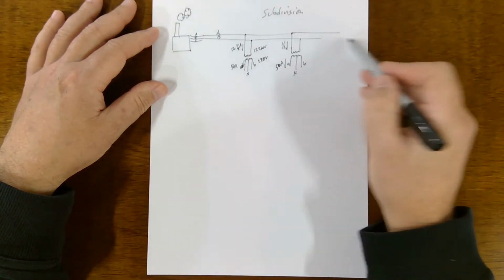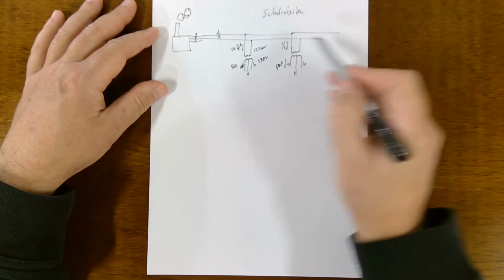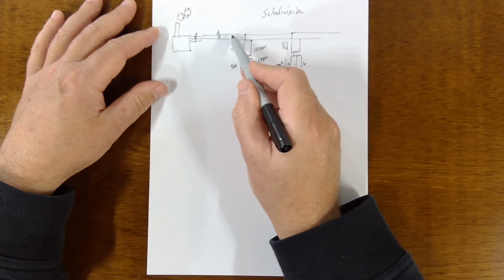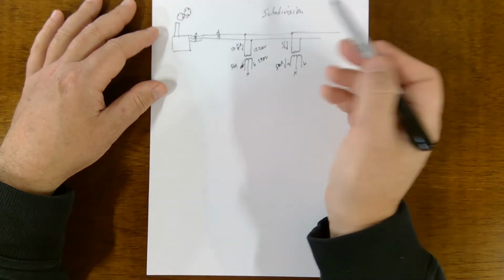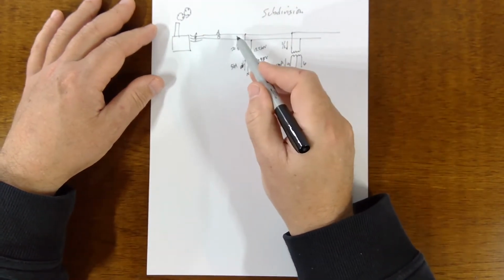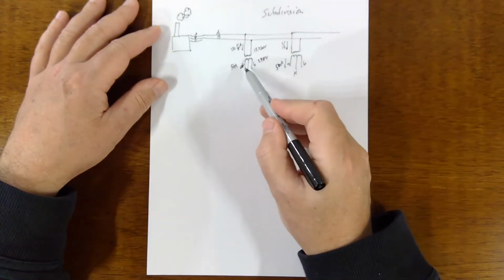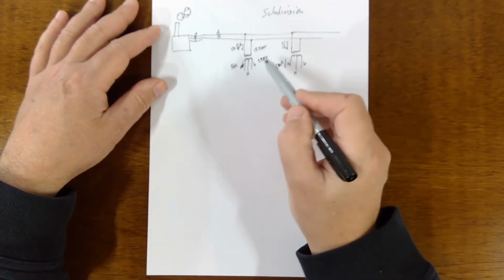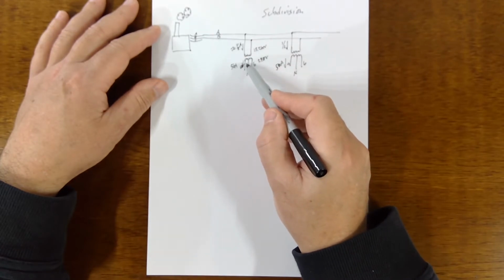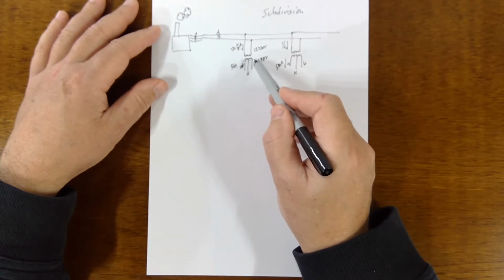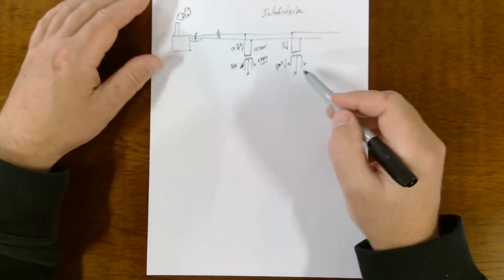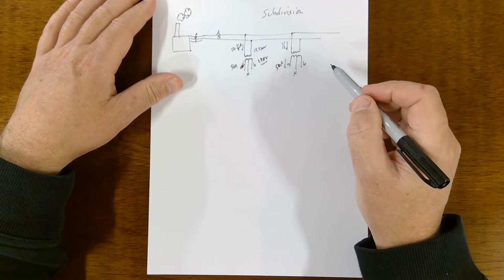And with all these other houses, there could be 100 houses on here, and you end up with a pretty good current on these conductors, maybe 100 amps. It would supply 200 houses. If it was half an amp per house, when you had 200 houses, it'd be 100 amps on the main lines at a high voltage. But then you're peeling off a little bit for each house and then stepping up the current and down the voltage to a safe voltage level. Anyway, that's what happens.